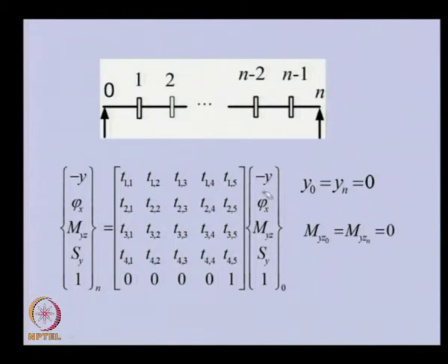and if there is unbalance in the system, the form of the overall transfer matrix will be this. So, the last row will be 0 0 1, these correspond to the unbalanced force. Other terms are multiplications of various point matrices and field matrices, and basically all these will be functions of omega, which is the spin speed of the shaft for forced vibration. For free vibration, these terms will be 0, and omega we can take as the natural frequency of the system.